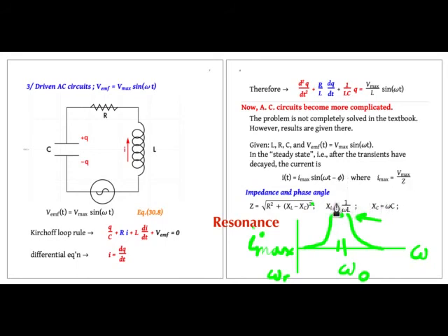And by varying the capacitance or the inductance, you can vary the impedance until you've reached the right frequency where the impedance of the inductor and the impedance of the capacitor are equal. Then you'll get the maximum current. That will give you the maximum reception. So this is the way radio communication works. Inside the receiver, there's an LC circuit, which is tunable.